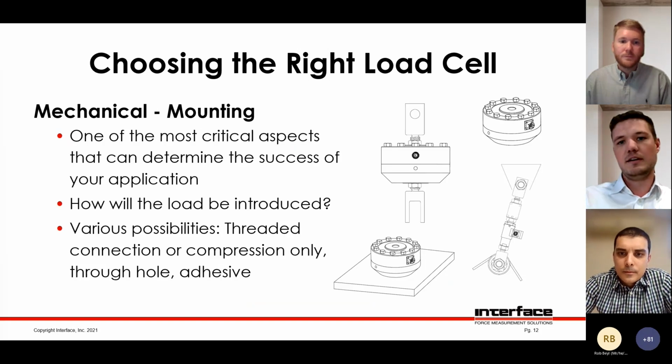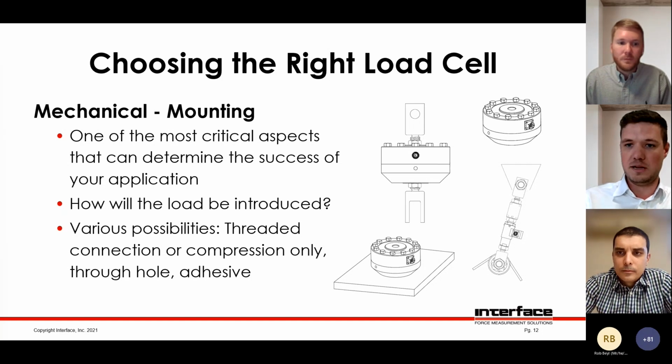Next slide. So with mechanical mounting, it is one of the most critical aspects, sorry, of mounting your load cell and of accuracy. Off-axis loads can produce very, very high errors, much higher than most other things like temperature or even the performance of the load cell.